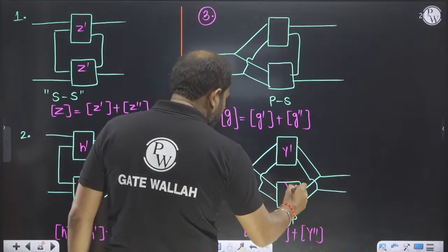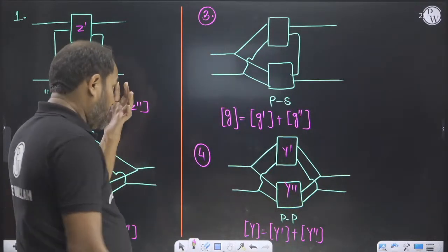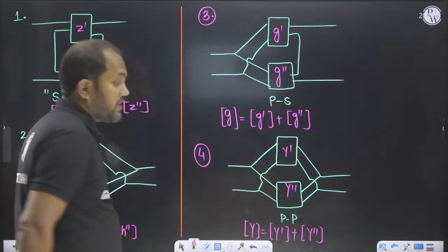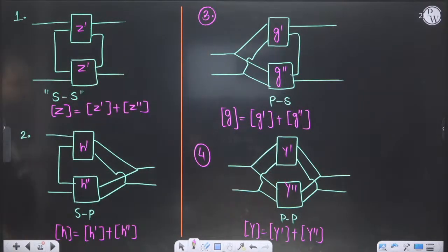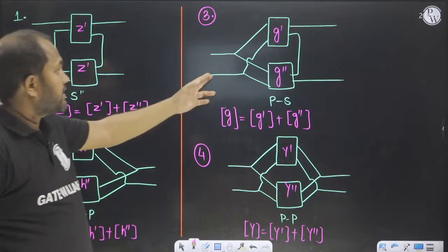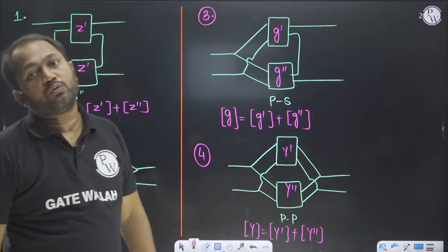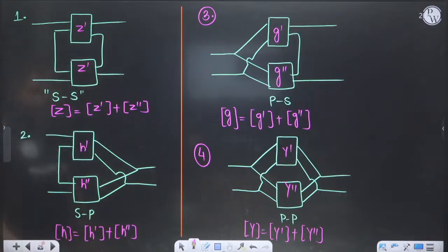So how do you know when we will use G parameter, H parameter, or Z parameter? Series KVL is Z parameter, KVL KCL is H parameter, KCL KVL is G parameter, and KCL KCL is Y parameter. So you can go through like this.